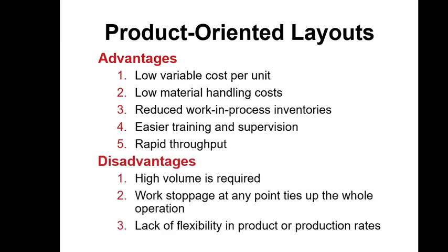Disadvantages also. Each type of layout has advantages and disadvantages. One of the disadvantages is that high volume is required. Again, this point we repeat 100 times. If you don't have a massive production, then it does not pay off, or it's not efficient for you to use this kind of layout. So you have to assure high demand and high volume in order to use this kind of layout. Number two, work stoppage at any point ties up the whole operation.